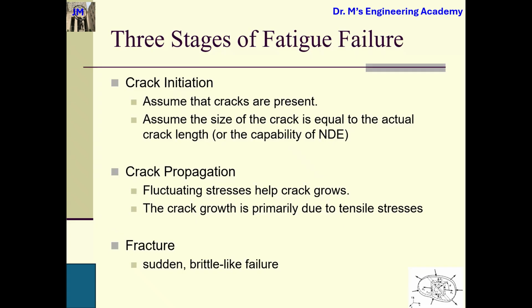And then we assume the size of the crack is equal to the actual crack length or the capability of the NDE. NDE means non-destructive evaluation, right? Non-destructive evaluation means that we have some means to detect the cracks in the specimen. Non-destructive means that you do not need to cut it, okay? If you cut it and then tell me, hey, there's no crack, but you already ruined the specimen. You understand, guys? That's called non-destructive evaluation.